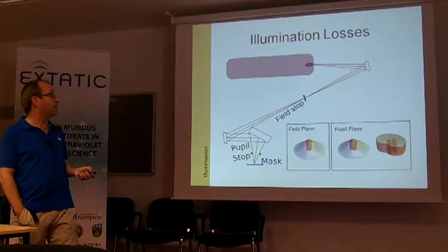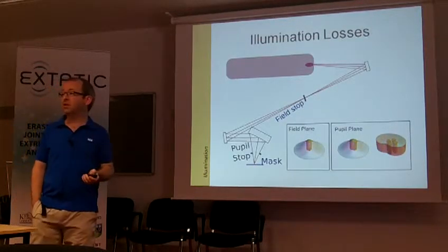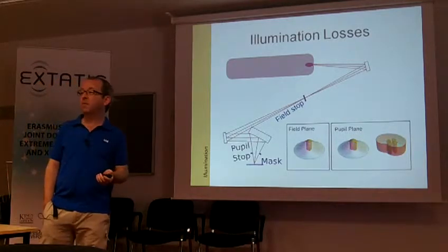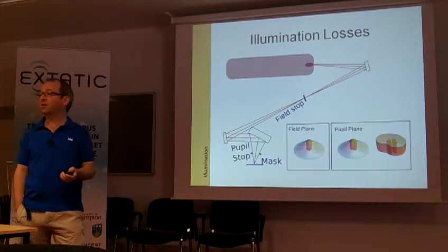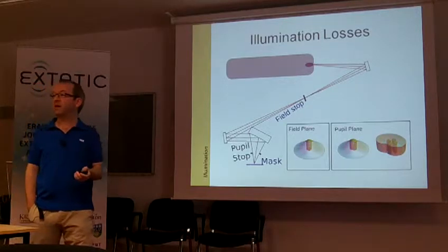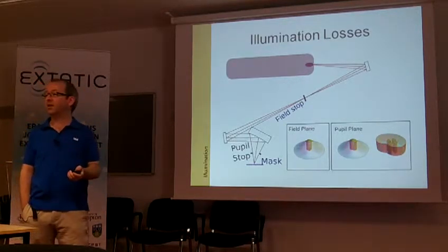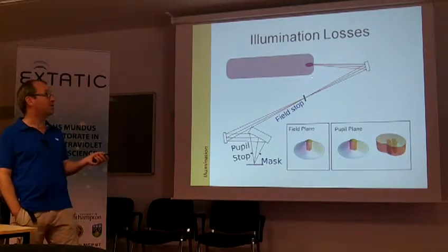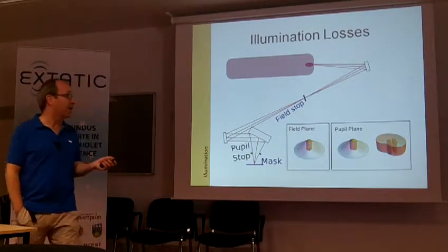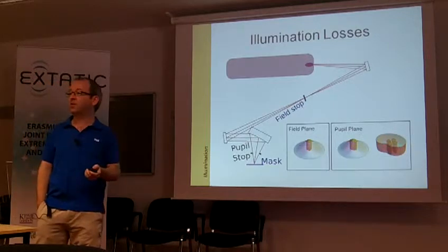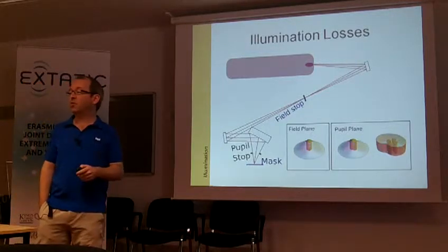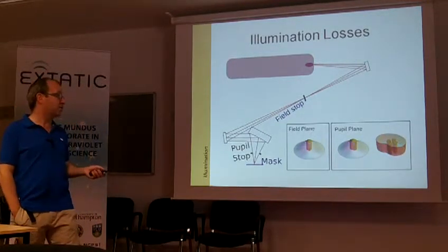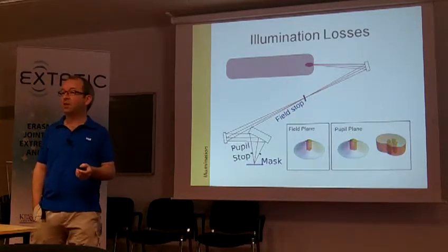So, in metrology systems for EUV masks, the challenges are even bigger, because their concerns in EUV metrology are to try and measure mask defects, and to do that accurately and consistently accurately, they need to have extremely tight tolerances on all of the imaging parameters. So they take the light source, which we struggle so hard to produce photons from, and they remove 95% of the photons with a field stop, and then probably remove another 90% of the photons with a pupil stop to illuminate their mask to give them the best possible resolution and the most consistent resolution.